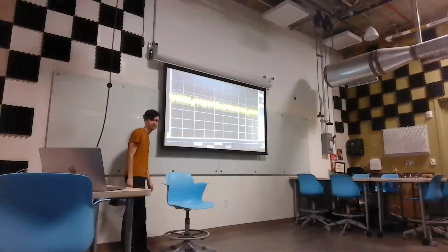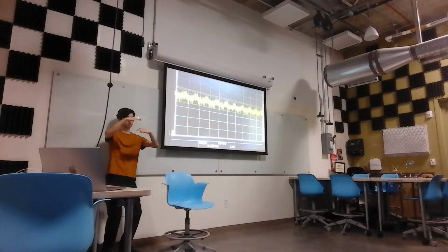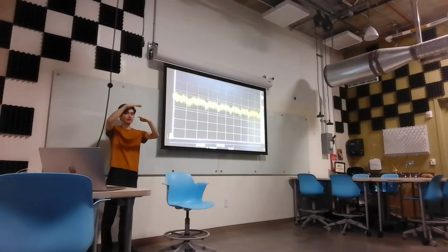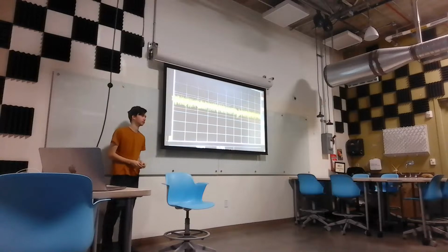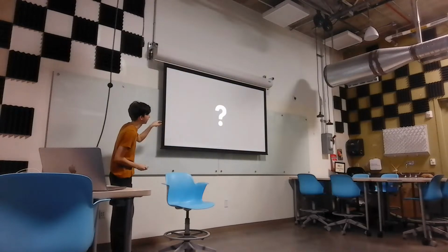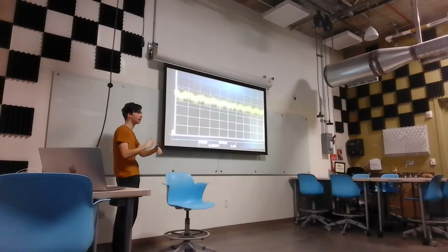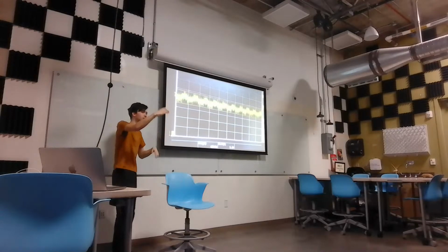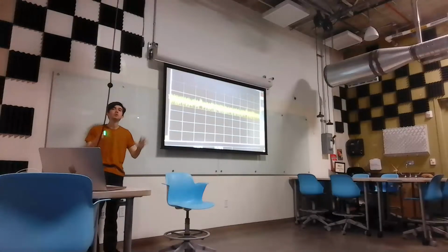Here's real life. As I change the power supply voltage, these two lines are moving, and it is solving for whatever proportion between them results in our target voltage. It's just great to watch that. As the line moves up, it starts using the bottom one more, then it moves back down, it starts using the top one more. And this results in a super smooth looking LED.